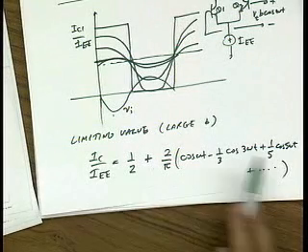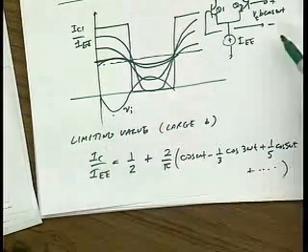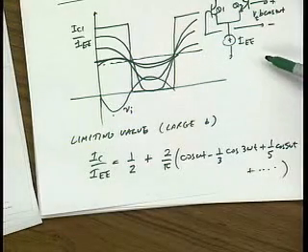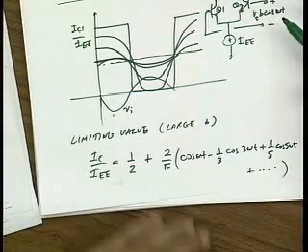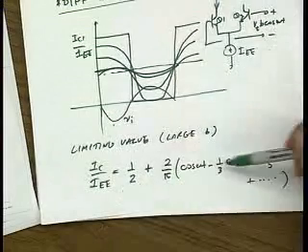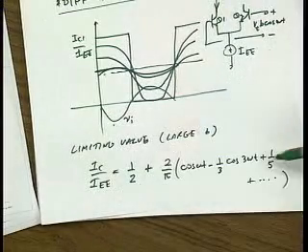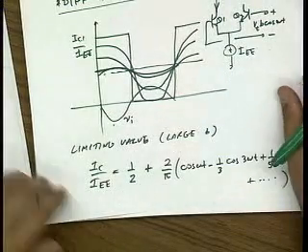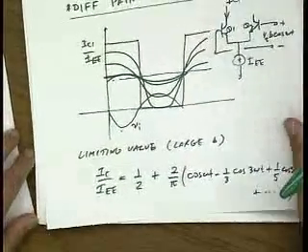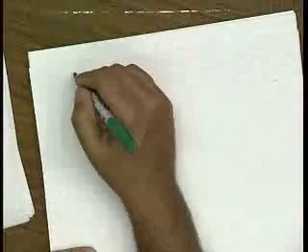Now, even though this is the limiting value, it turns out that if you put a few hundred millivolts across this differential pair, you get pretty close to this squarish waveform. And this is very convenient for doing simplified analysis, hand analysis. Okay? If you want to be more accurate about it, you could just write down a few equations.